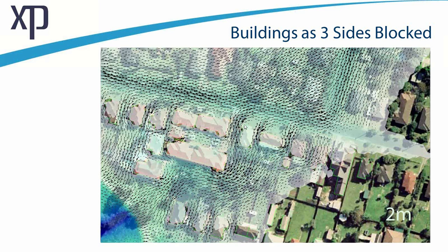You can, of course, raise the elevations as house pads. So, for example, if these are slab-on-ground houses and they're 0.3 meters typically above ground level, you can actually modify the ground elevations to represent that so that they only flood once the water gets to that depth.